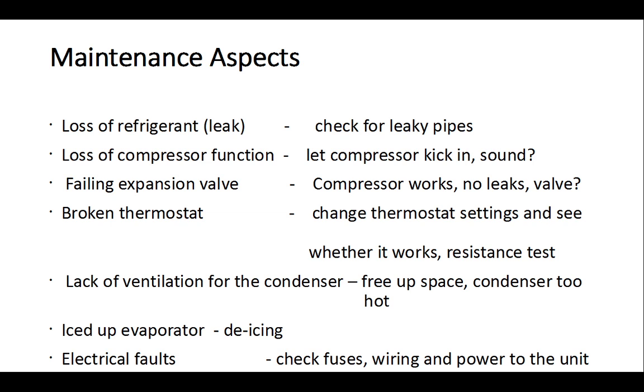Electrical faults, obviously check fuses, wiring, and the power unit itself. There isn't much electrics within refrigeration other than the thermostatic control and just powering the pump, and that's really all it is. It's not much to it. But again, it can go faulty. It can just be a dodgy contact or a fuse that's gone or something like that.